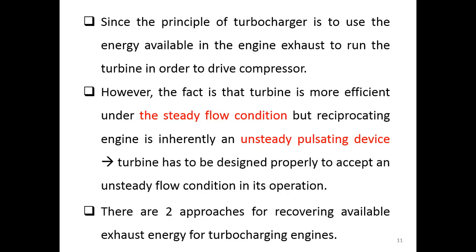The turbine requires a steady flow in order to be more efficient, but the exhaust, which is the energy that we use to run the turbine, is an unsteady pulsating flow. So in order for our turbine to be able to work under these flow conditions, the turbine has to be designed properly, so that it can accept this unsteady flow condition in its operation and still work well.